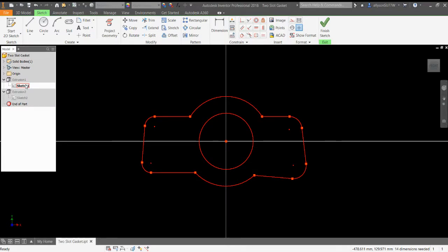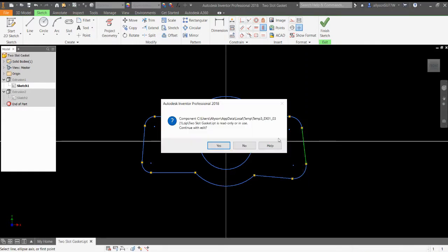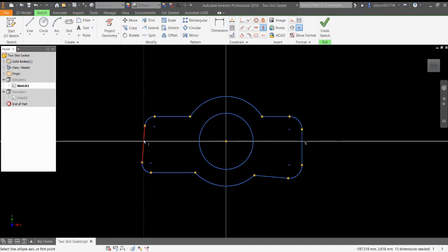For me, I want to use my easiest constraints, which are vertical and horizontal. I'm saying easy because I'm looking at my picture, and I have some things that are vertical and horizontal. So I'm going to start with my vertical constraints. So I've made these vertical.